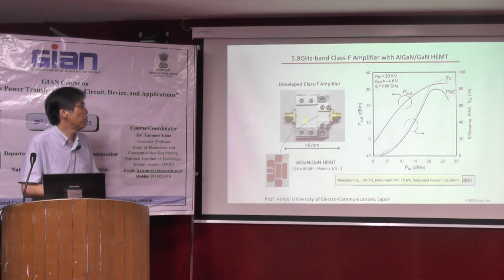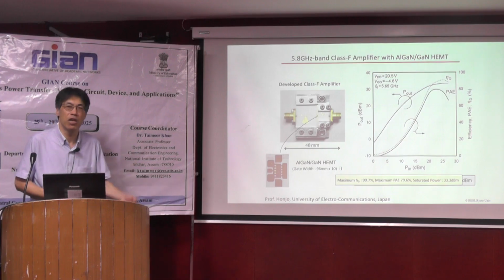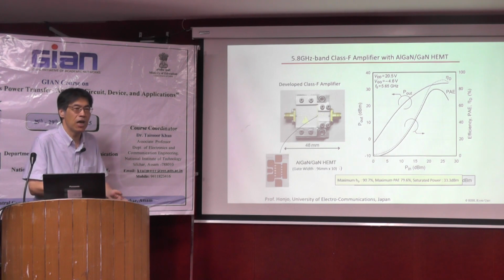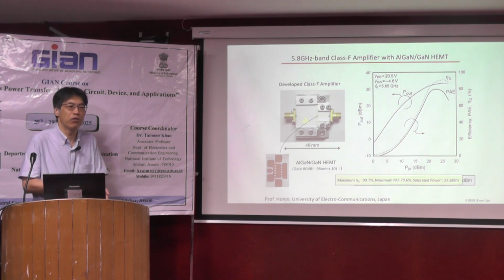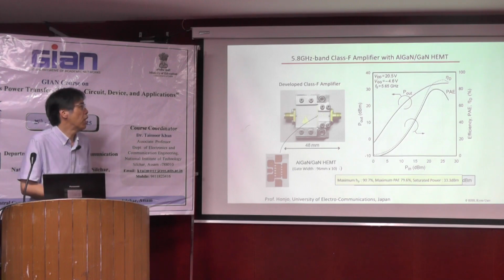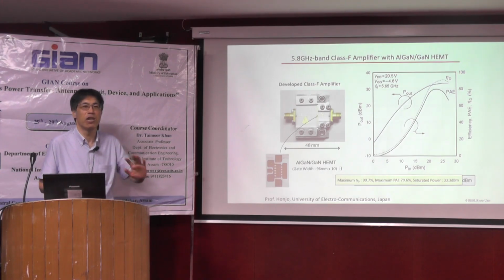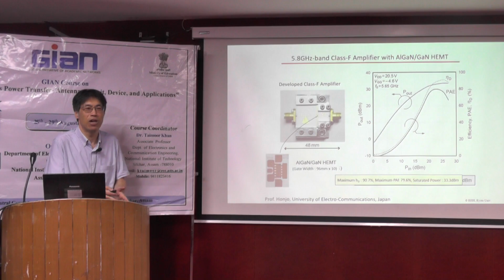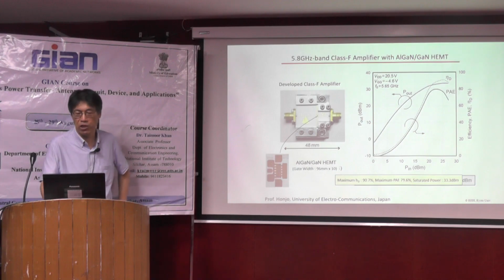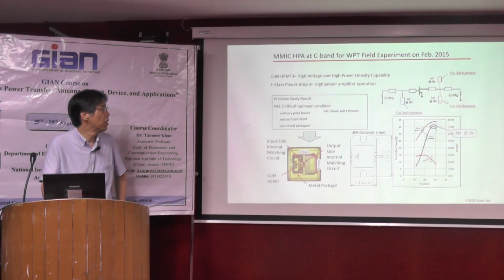So if we would like to apply this class F or class D or class E, we have to consider how to keep the high efficiency, but also how to increase the bandwidth. It's a very difficult problem. But this class F amplifier is suitable for wireless power transfer, because there we don't need any bandwidth to carry the electricity on the radio waves.